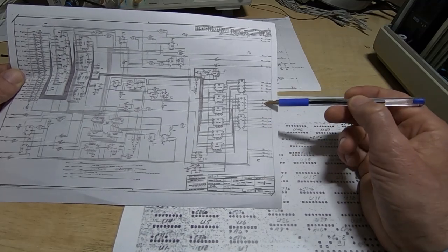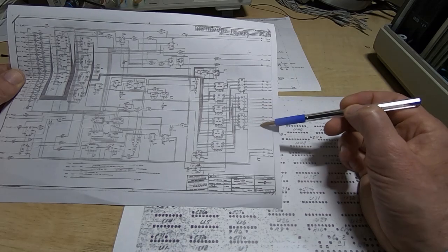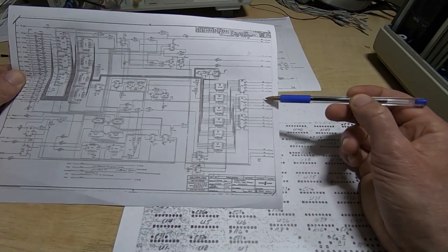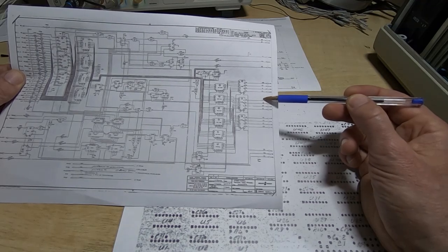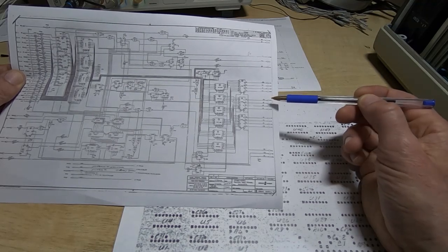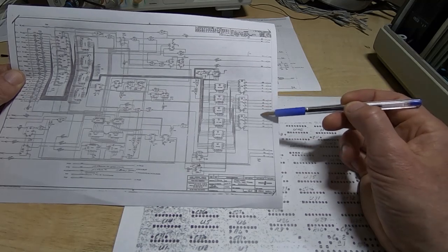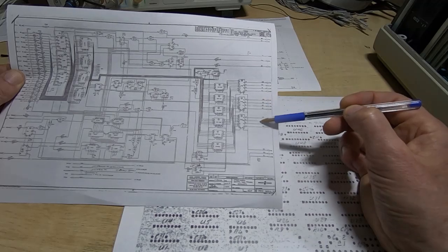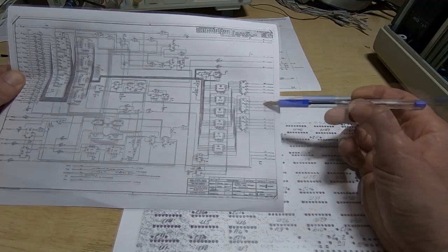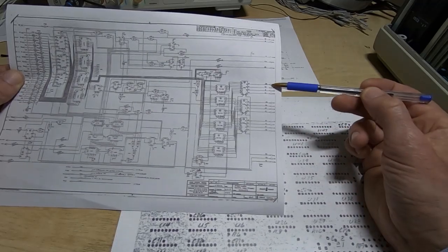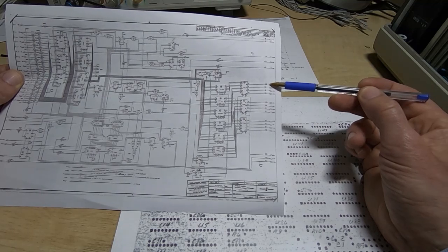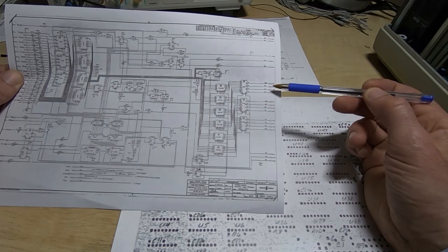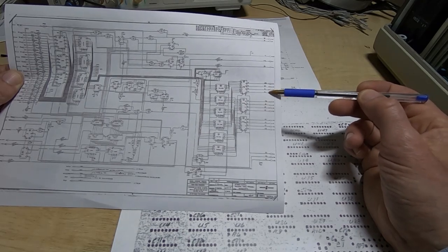The lower 7 bits are for our standard ASCII code. The 8th bit is the chip select bit that we repaired in the previous video, and that gives us the ability to select one of 2 character ROMs, so effectively gives us an 8-bit value for 256 characters rather than 128. And the upper 4 bits are used for either cursor control, inverting the character, make it inverse video, making it blink, or underlining it.